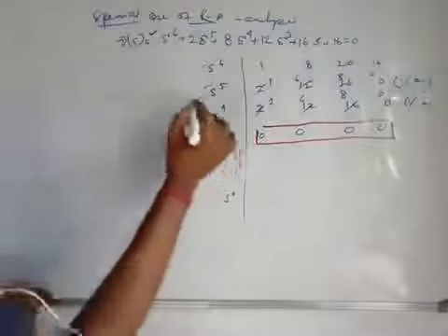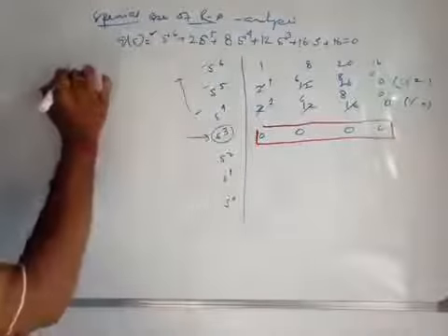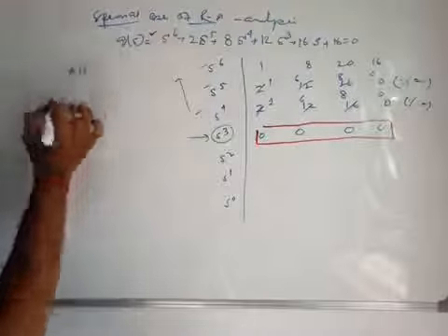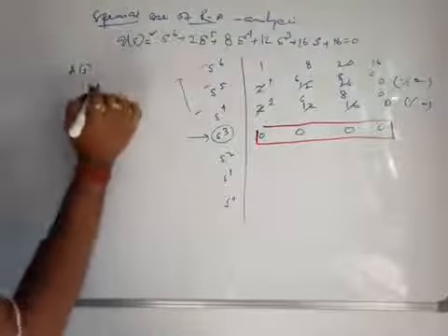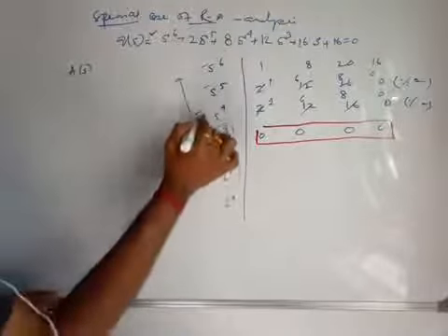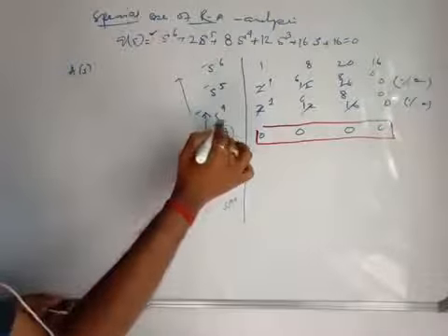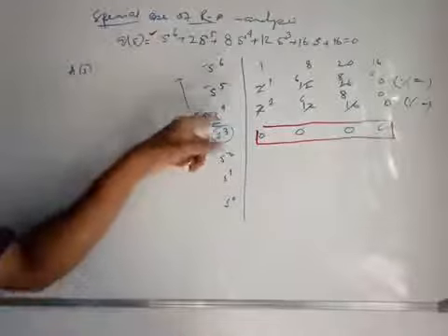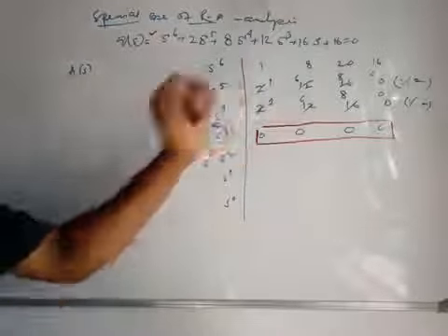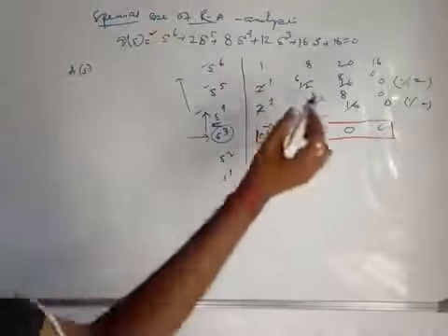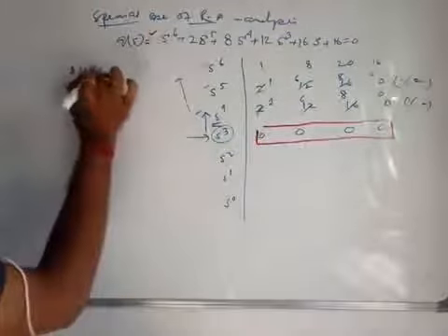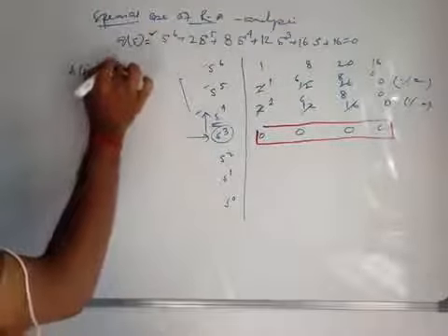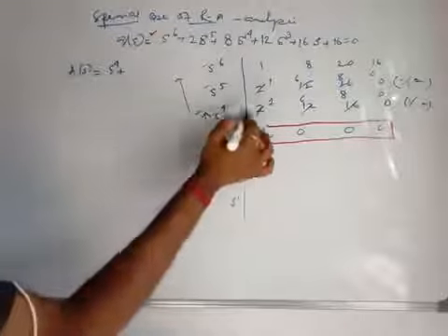And once this kind of problem arises, what Routh proposes is that you have to consider one auxiliary equation, considering the previous row, that is the row of s to the power 4. And what are the elements of s to the power 4? You see, this is 1 6 8. So the auxiliary equation will be s to the power 4, that means the coefficient of s to the power 4 will be 1.